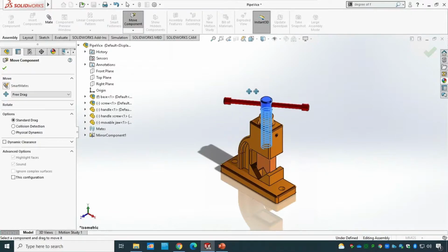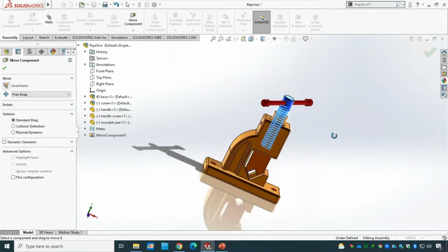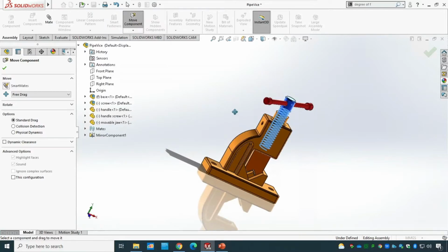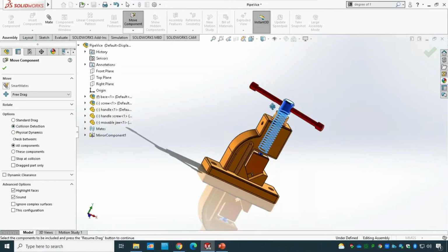If you have a look, from now on, if I screw back, my model basically goes inside of the assembly. I'm not happy with this one. To see the collision, you can click here and move that one around from a point, and you can hear a beep noise, which means there's a collision and it's trying to prevent that movement.